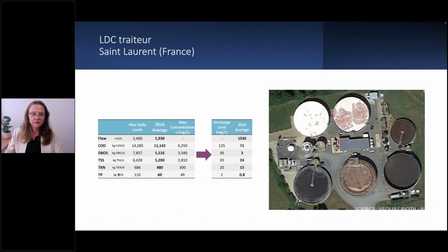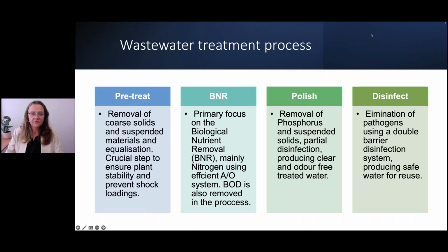So we have a sequence of processes that start with a very, very good pre-treatment where we remove up to 95–96% of all the suspended solids. In this stage, we can also remove nitrogen because you are taking the protein, the solid part of nitrogen. So you enter the wastewater treatment process with a very clarified water, mainly with dissolved contaminants or nutrients.